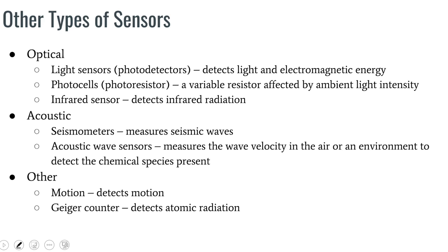And the other thing to remember is many of these sensors may either be producing analog signals as voltage changes, or some may even produce the actual digital output of the information. Say, for example, there may be some temperature sensors where the output is some voltage changes, and then you will have to convert that into appropriate temperature values using some conversion algorithms, conversion equations in your program, in your control system program.